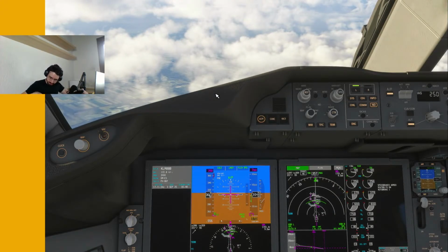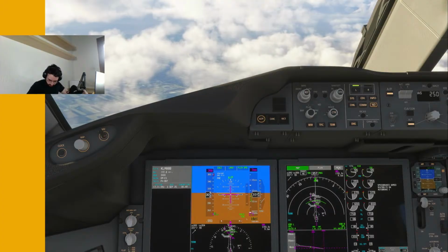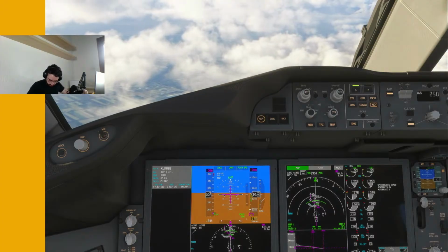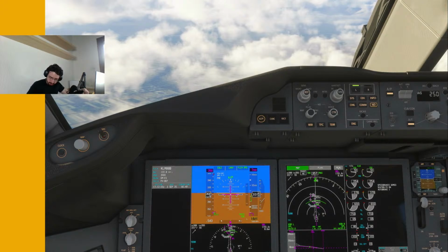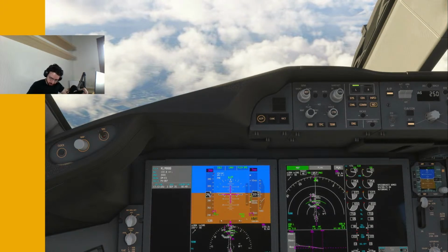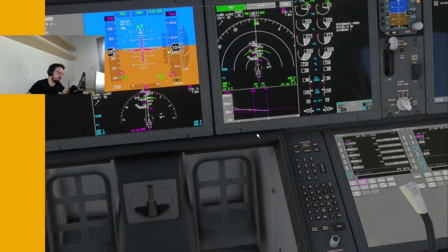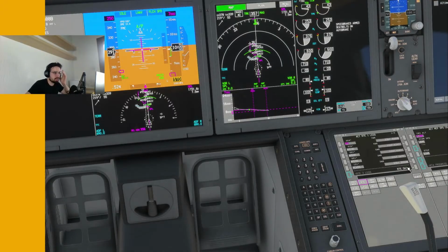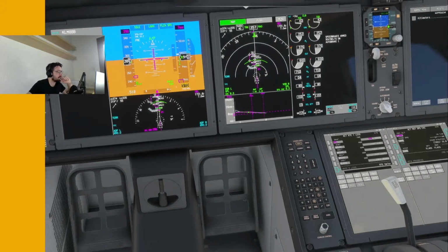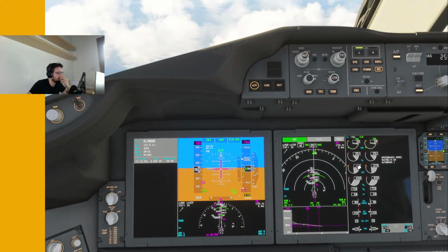So after Sierra Papa Lima, I mean, I don't see any ghost rain, to be honest, so I guess we can descend. Go around is 3,000. Let me see here if we have some constraint. No. We just have to be above 2,000 at Pebble, so we can descend 2,000 after Sierra Papa Lima.